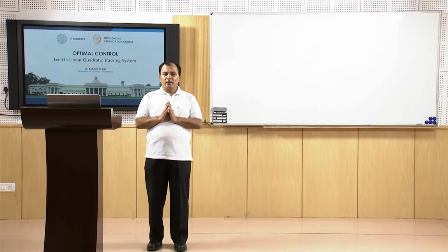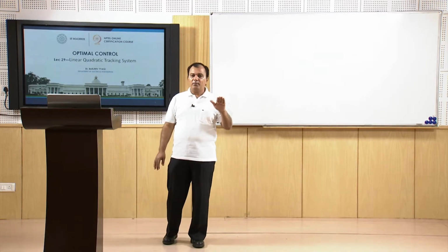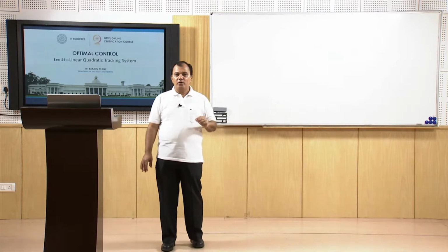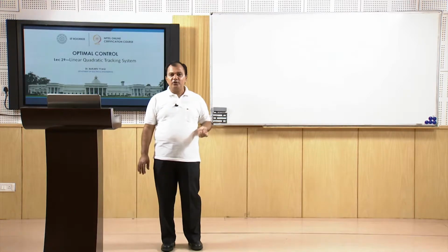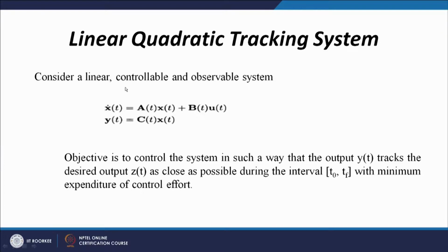In the tracking system we will try to follow whatever my reference input is. So this means R will not be 0, and the system is subjected to track how my R will change. We can consider an observable system. This is the primary condition to design a quadratic regulator. So my system should be controllable and observable.